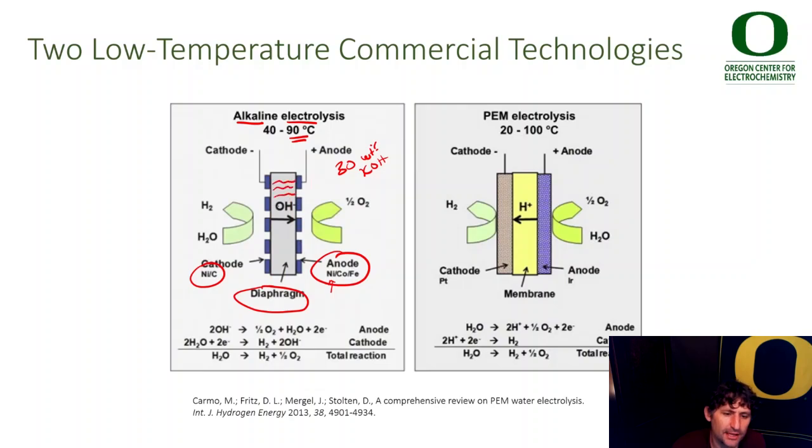Okay, and there's actually a lot of research and development needs right now in creating better diaphragms for these sorts of technology. But essentially, it has a thickness of maybe 200 microns or so, and it consists of pores maybe 150 nanometers in dimension. So fairly large pores compared to the size of the ion.